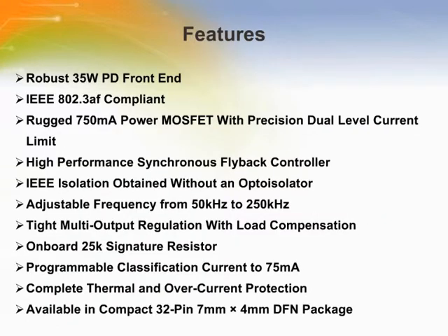Linear Technology introduces the LTC4268-1, a power over Ethernet interface controller with a synchronous, current mode, switching regulator for delivering precise regulation and high efficiency to power-hungry power devices. The LTC4268-1 provides up to 35 watts for 2-pair systems and as much as 70 watts for 4-pair systems.